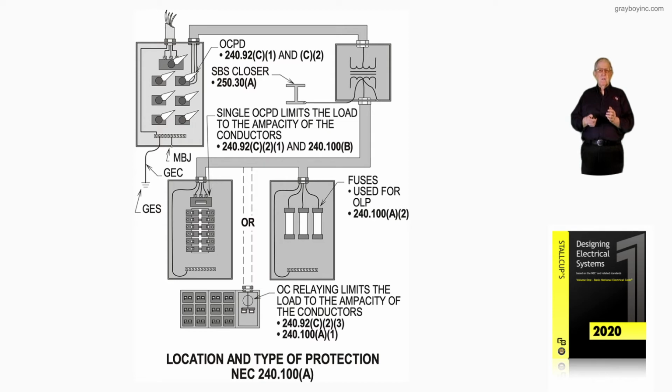So you're placing the relay system in such a manner that the relay upstream is either comparing, usually, or communicating with that relay downstream to provide the protection scheme. So here we're either using circuit breakers, fuses, or relays, showing you all three in one drawing.